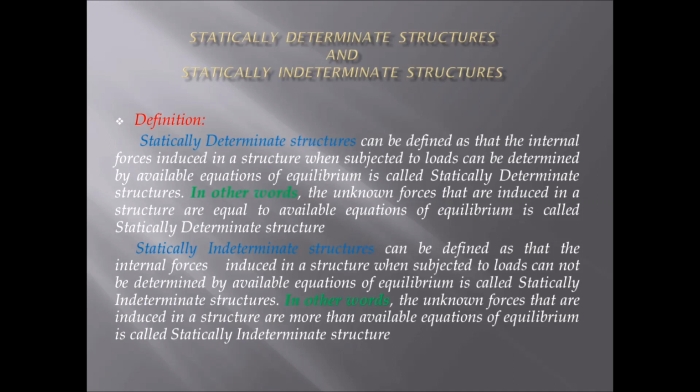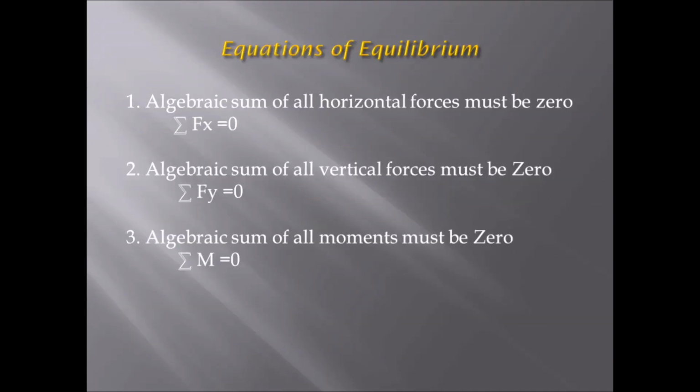Statically indeterminate structure can be defined as one where the internal forces induced in a structure when subjected to loads cannot be determined by the available equations of equilibrium. In other words, if the unknown forces induced in a structure are more than the available equations of equilibrium, it is called a statically indeterminate structure. Before that, what are the equations of equilibrium that we should know?